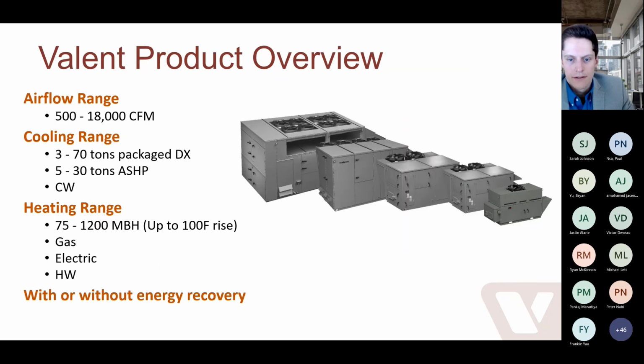So one final slide here, just to talk about Valent a little bit. Valent is a DOAS unit manufacturer, and we've got several different cabinet sizes. We go from 500 to 18,000 CFM, and we do package DX, air source heat pumps, chilled water, and on the heating side, we do furnaces, electric heaters, hot water, steam coils, again, air source heat pumps, and we can provide all of our units with or without energy recovery.